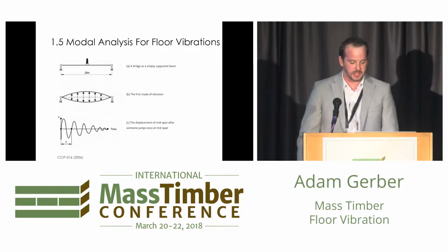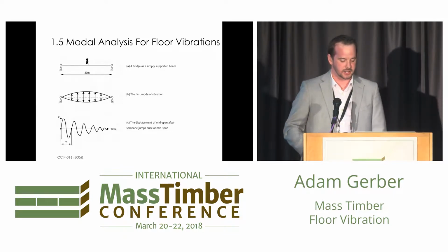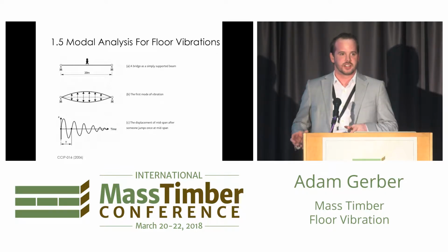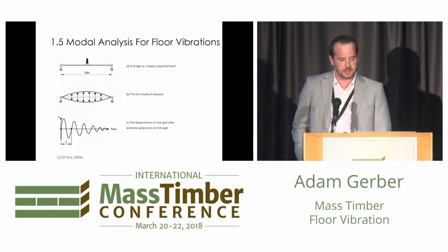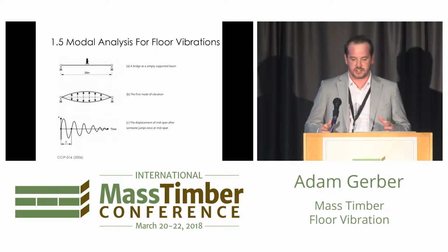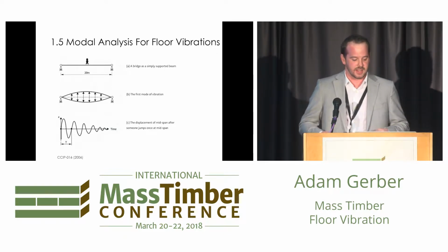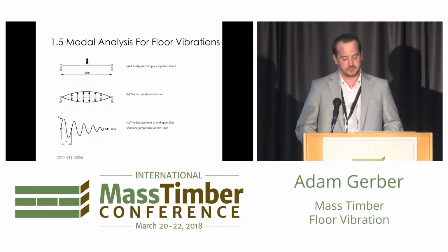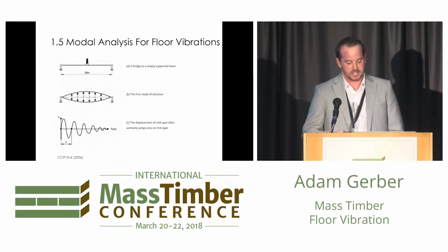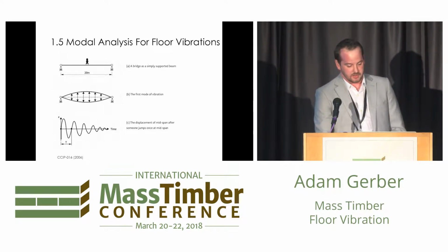Many people are probably familiar with modal analysis from earthquake engineering and dynamic analysis of structures for seismic. Hopefully we can shift your focus to floor vibrations, and a lot of the principles are virtually the same. If we take an example of a bridge or a simply supported beam, the first mode shape would be the deflected shape of the beam. If you push it down and allow it to release and vibrate freely, in the bottom figure you can see that the displacements and the associated accelerations eventually go to 0, and they oscillate back and forth.